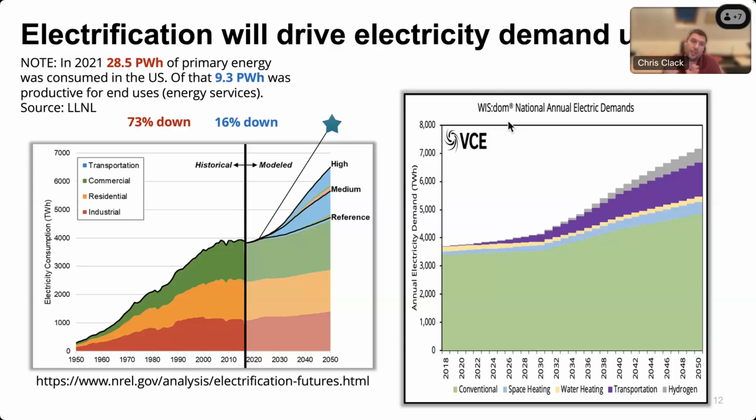And when you bring the electrification in, the reason we need to start thinking about distribution is that a lot of these assets will be added in the distribution grid. And when I talk about distribution, I'm talking anything below 69 kilovolts. But really what I'm thinking about is customers that are plugging in their EVs, or they're putting an air source heat pump in, or a ground source heat pump, or an air source water heater, and how we may be able to use that along with some distribution assets to actually drive down the need for other assets on the